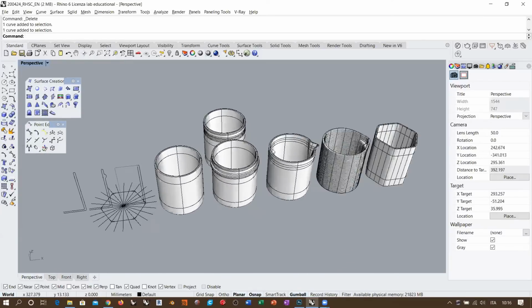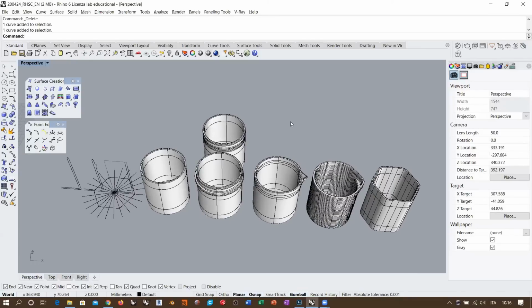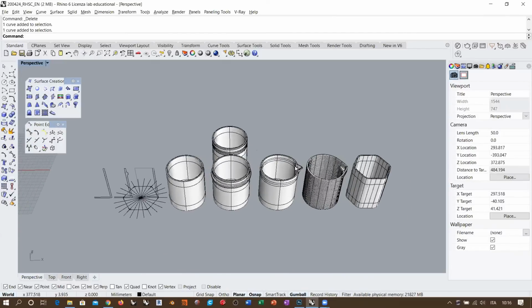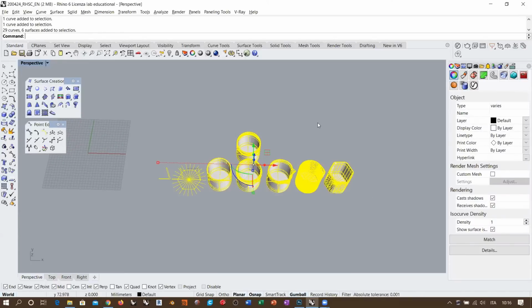And one last observation. Yes, it's very easy with sub-D to produce some organic design, for example, but in my personal approach, I wouldn't rely on sub-D for creating extremely controlled surfaces, like, I don't know, automotive design or something like that. Okay, it's very easy to create something that resembles the shape of a car, but I wouldn't use sub-D to create the shape of a car. Okay, so it's a nice tool for starting to play with subdivision surfaces, but I prefer to work with other tools in that case.